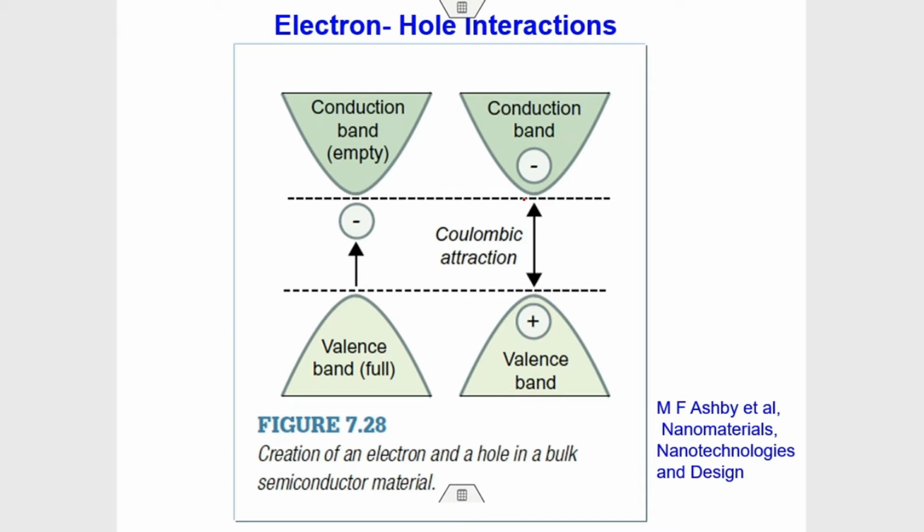So, if I have a photon falling on the valence band, electrons in the valence band will absorb the photon energy, and then if it can jump from the valence to the conduction band, then it will do that, provided the photon has sufficient energy to cross this barrier of the energy gap. Now, this transition will obviously lead to electron movement from valence to the conduction band, and then the electron can come back also and lead to a photon. That is what we have discussed now.